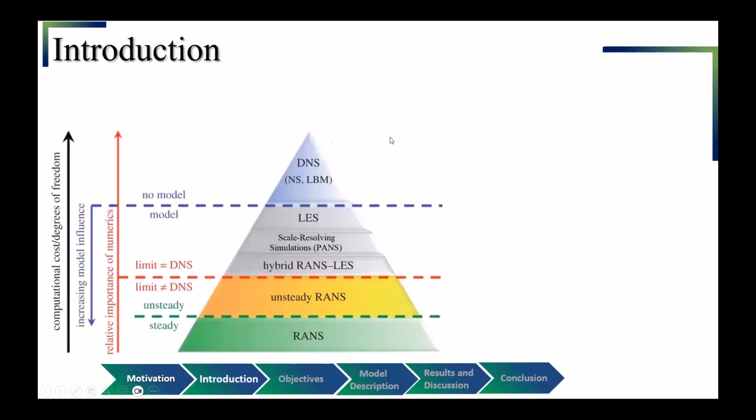So starting with turbulence modeling, the RANS methodology is computationally efficient but limited in capturing the full range of flow physics, coherent turbulence, due to its one-point closure approach. DNS and LES techniques provide accurate computations but may be computationally overwhelming for